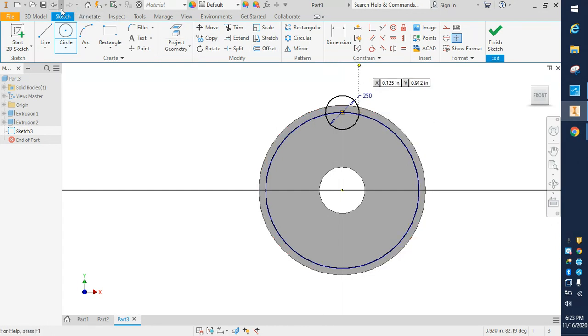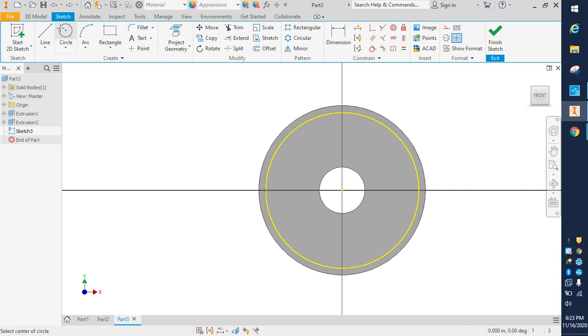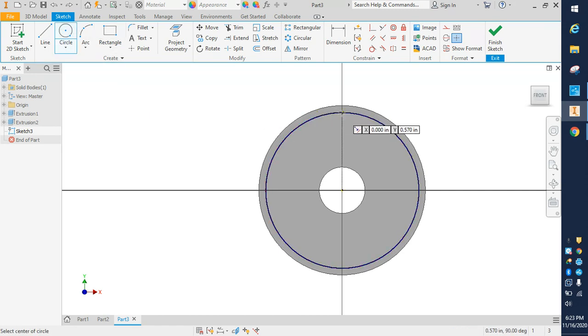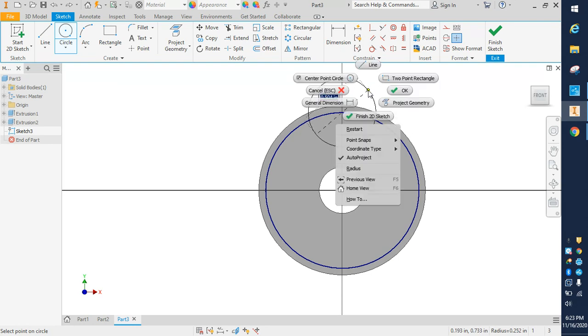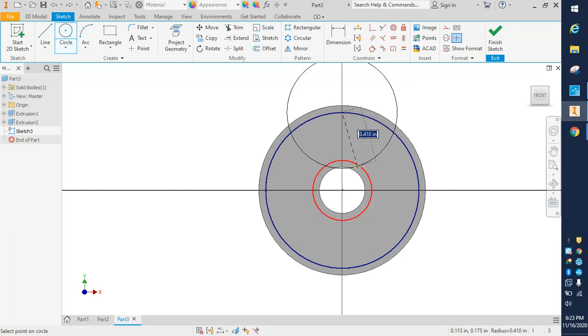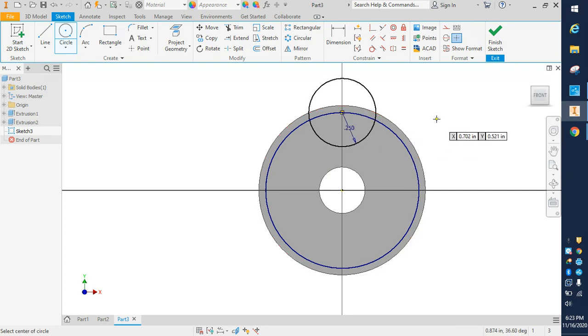We're going to show you one other tool here that is kind of a new thing for us. We're going to draw our circle again, but before I dimension that, notice how I'm in diameter. I'm going to right click, and with that, I can change my dimension to a radius. A radius. So if I look at that drawing in the packet, it shows that that's actually a radius of 0.25. All right, that looks to make more sense.